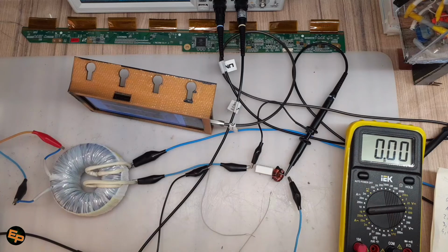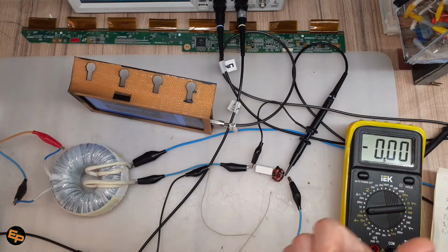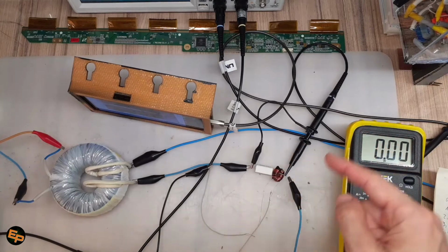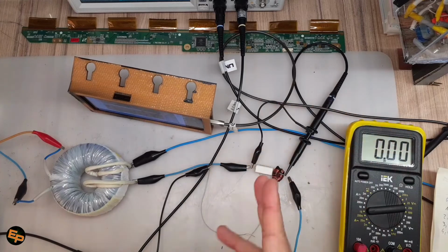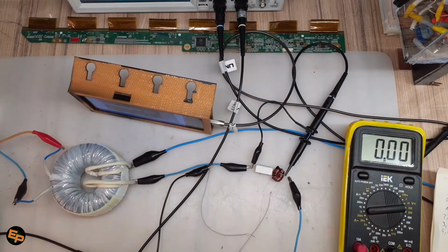And on the right end of the screen, but outside of the screen, I have a very rudimentary artificial load where I can basically set a few power resistors on and off, and in function of what resistance I set over there, I will draw a smaller current or a larger current in this whole circuit. And of course we have a multimeter here set to measure this AC current, so we can have a clearer measurement on top of actually seeing the waveforms themselves on the oscilloscope.